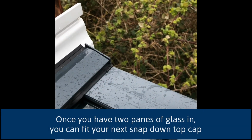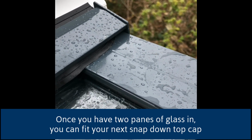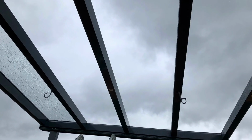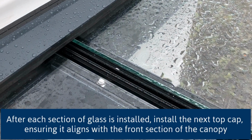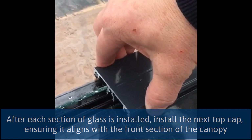Once you have 2 panes of glass in, you can fit your next snap-down top cap as shown. After each section of glass is installed, lean over through the gap and then install the next top cap, ensuring it aligns with the front section of the canopy.